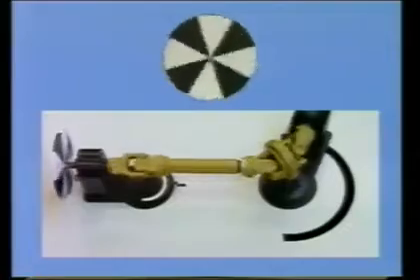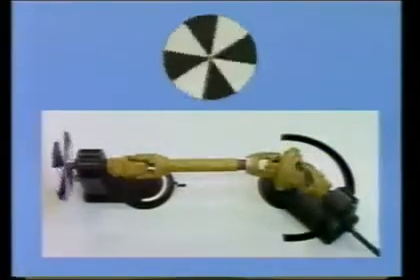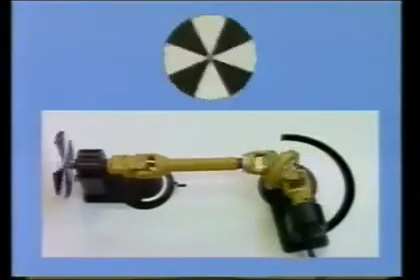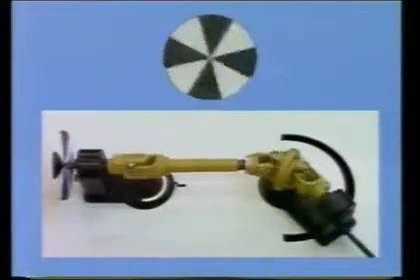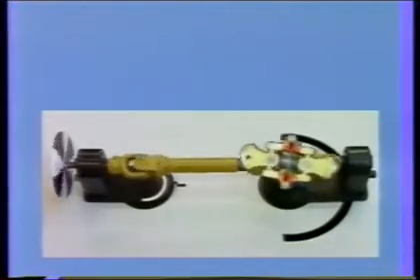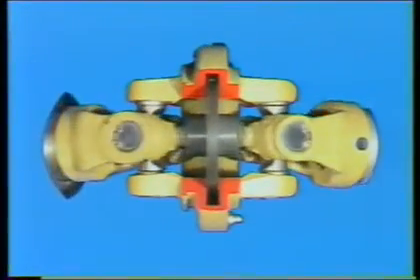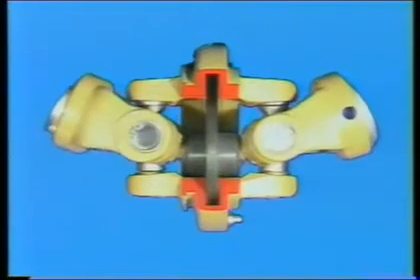Corners can be taken easily with the PTO shaft switched on. In the case of the short hitch, such corners can only be taken with a wide-angle constant velocity joint. In this instance, a simple joint would lead to pronounced velocity variations and oscillations, and thus to wear and destruction of drive elements.